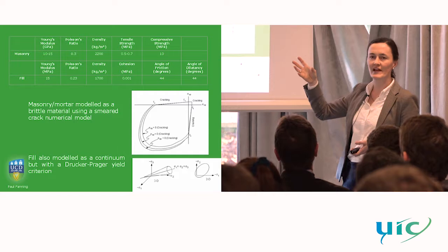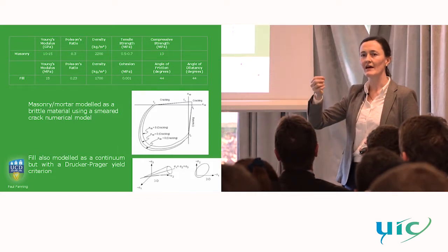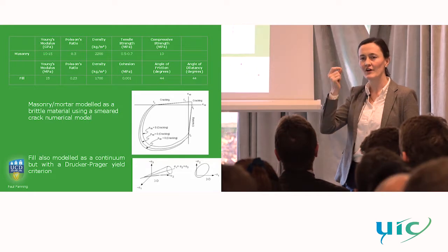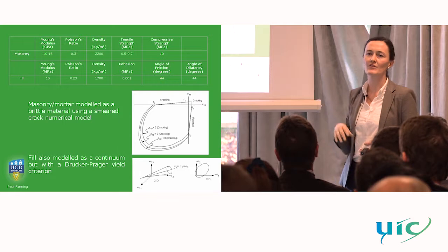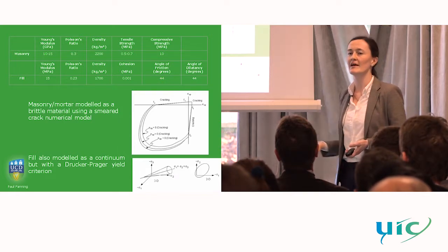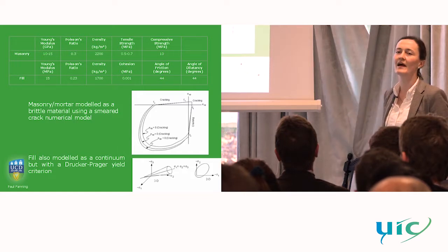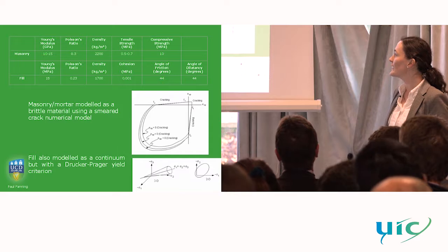Once it reaches that tensile limit, you're reducing the stresses down to a very small value where they've occurred and redistributing them locally. You can't reduce them fully down to zero because it'll create numerical instability in your model, so it gets reduced down to a very nominal value.